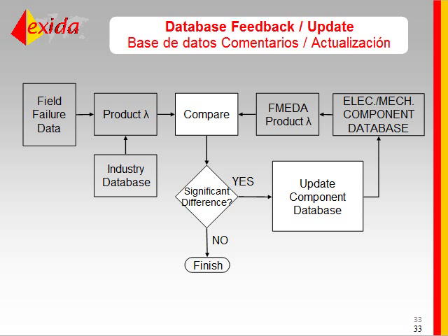that you can compare to field failure data, even when you don't have as much field failure data as you like. And what I mean by that is often you need a lot more data points to get failure modes than total failure rate. So in many cases, we're able to gather enough field failure data to calculate a product failure rate. And of course, one must compare that then with the FMEDA results.